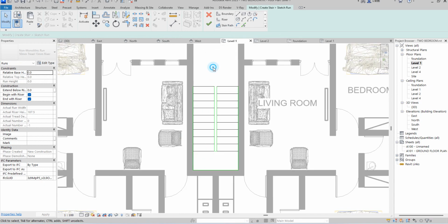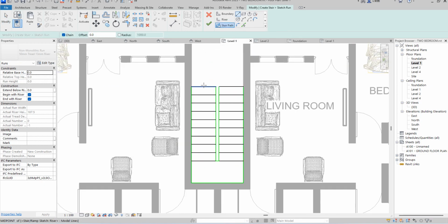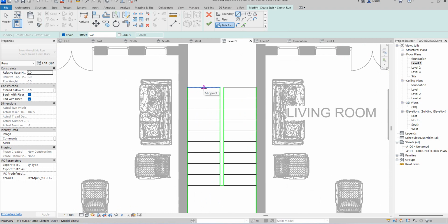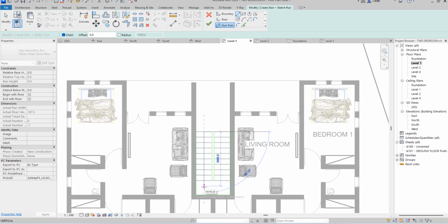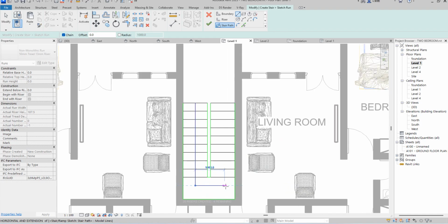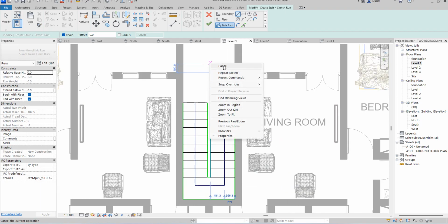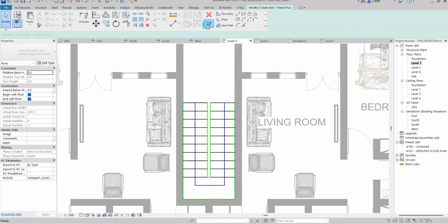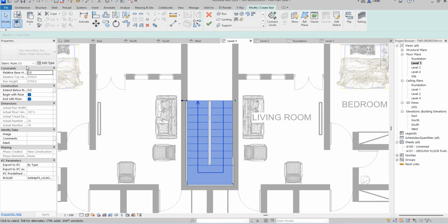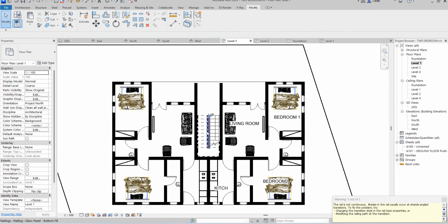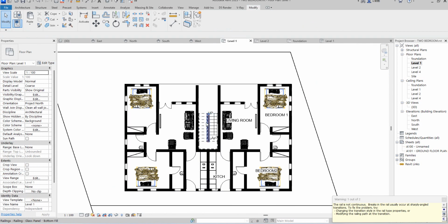So what you need now is that you need to sketch the stair part. How does it flow? It does not matter, you can just change the direction anyhow you want, but one thing is that you must give the path that this stair follows. So you do that by using this and come up with this and you finish it up here. So I think with this one you have done. So when you click finish, something is supposed to be animated. So now you do this one in place, then you finish this. That is the highest level of what you have done.